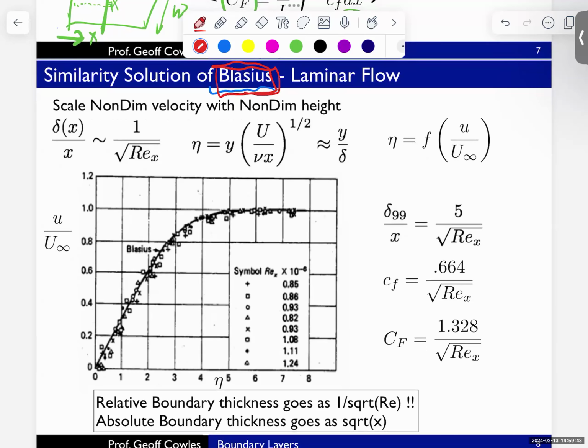So what Blasius did was solve for a closed form solution of this. This is an actual closed form solution of the, not Reynolds averaged, the Navier-Stokes equations. He took the Navier-Stokes equations for 2D steady flow, and then made a couple other assumptions that you can argue about boundary layers, namely that the U velocity changes more rapidly in the Y direction versus the X direction, and that changes in the V velocity, the vertical velocity, are relatively small.